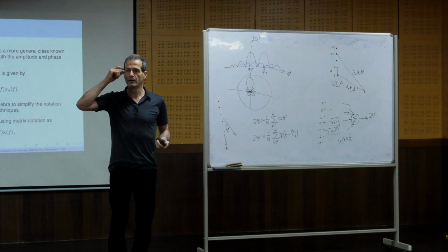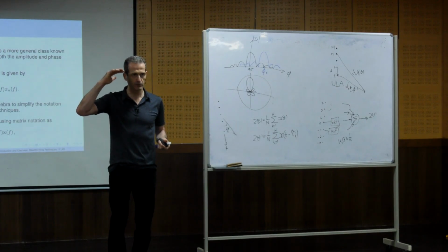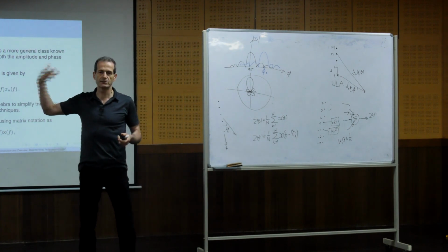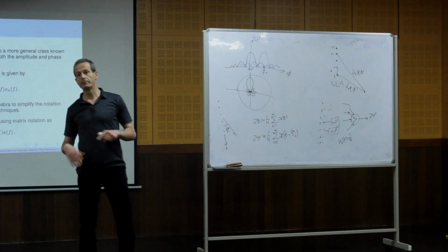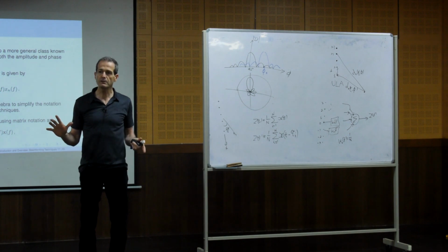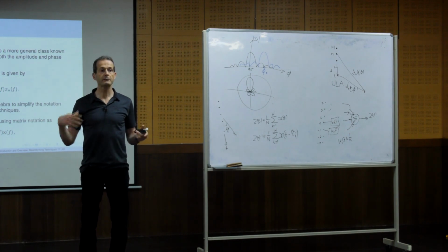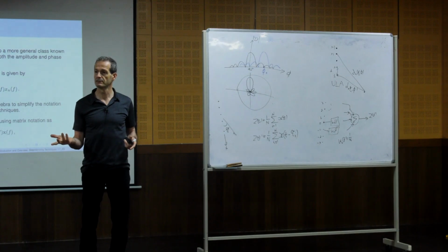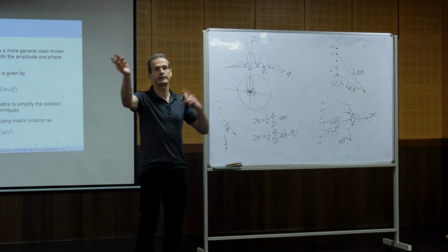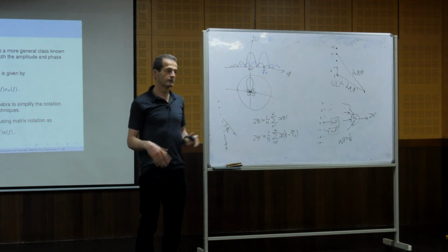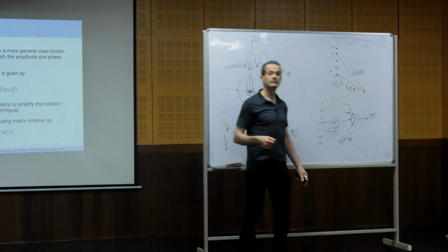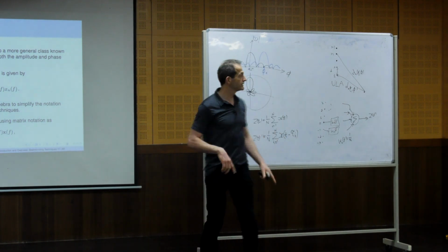Suppose that I design a fixed beamformer for the smart glasses, and I don't know if the noise comes from this direction, from another direction, or maybe from all directions. So the simplest way to design a fixed beamformer is to design a beamformer that maximizes the directivity. Because I don't know in advance what the noise will be, I assume that it can come from any direction. So it makes sense to design these weights such that they maximize the directivity, the ratio.